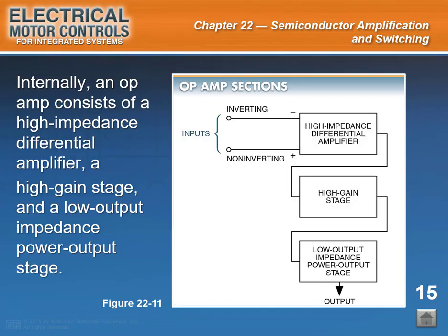The high-gain stage boosts the signal voltage level considerably. The power output stage isolates the gain stage from the load and provides power with a very low output impedance that allows for a high current drive capability without much voltage drop.